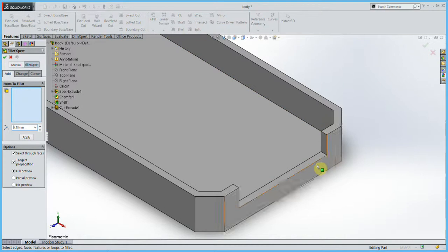And now we need to select the two lines that we're doing. So it's between this surface and this surface, it's that line here, and the line appears even though we can't see it. I can click on that line as well. If we actually hit a wrong surface or another line, all we need to do is click on it again.